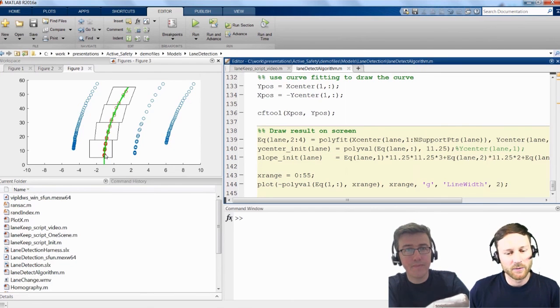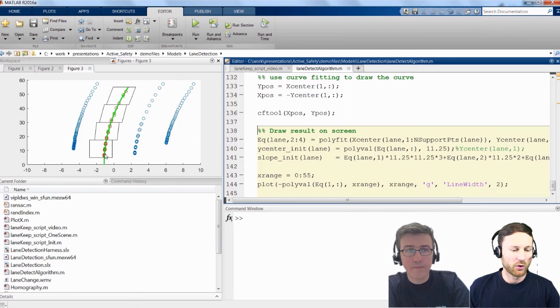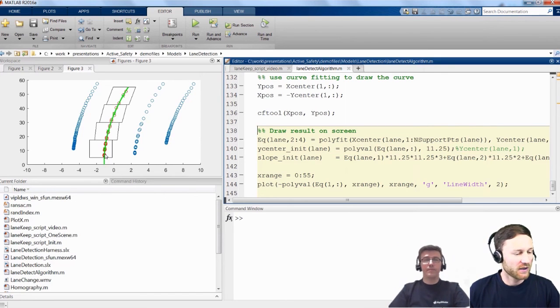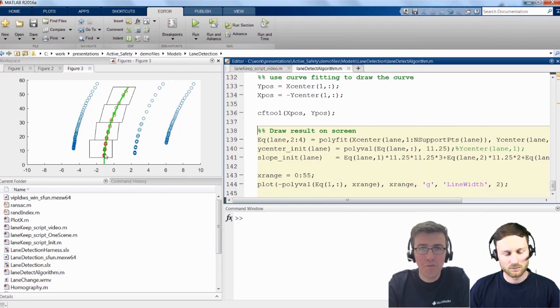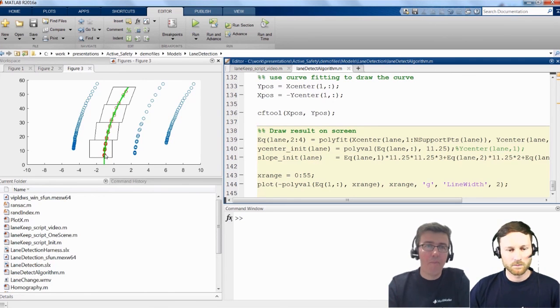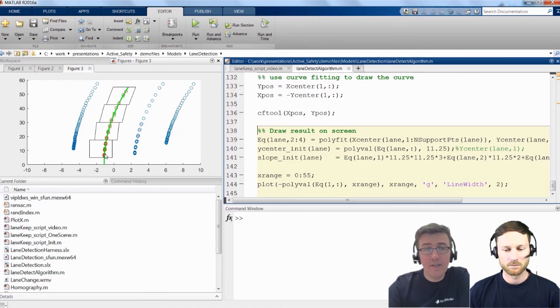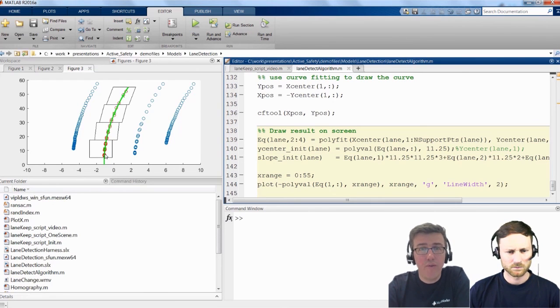Well, quick question here. In that case, you used a quite low order of a polynomial to specify a curve. Not sure whether all chicanes at a Formula Student racetrack can be covered using that, but well, it would be no problem to go for higher order polynomials or even for stepwise functions. Yeah, that's a good point. This is something you have to check. So the second degree is okay on not too complex roads, but maybe you will have to select something else in the tools that we have seen before. And now this result and this analysis is something that we have done for one frame.